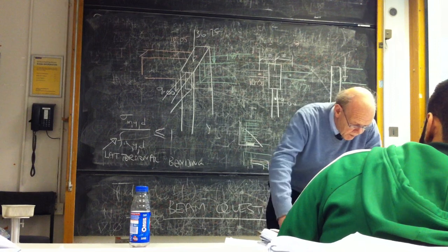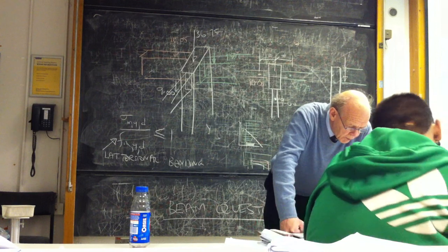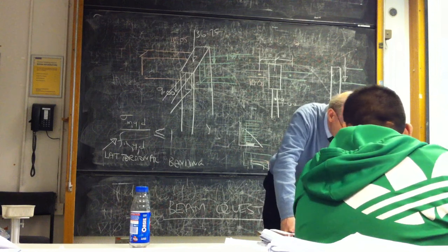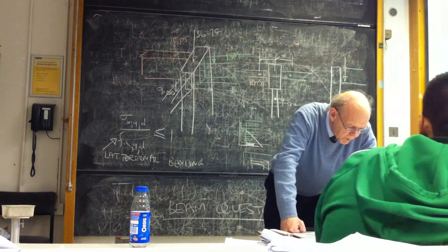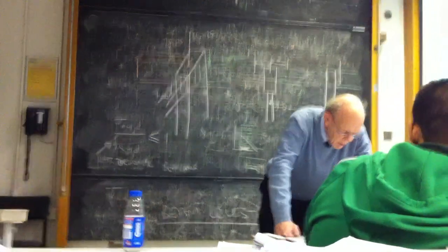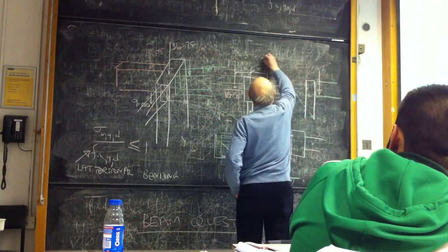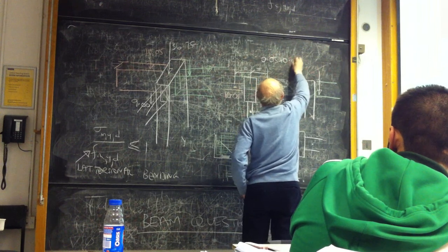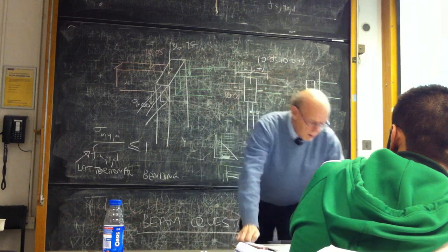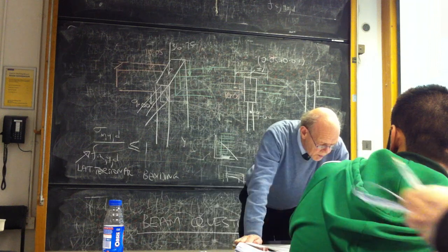Right, so what have I got? I've got the axial load. I've got the actual compressive stress at 0 degrees to the grain, 3.12. I've got the bending moment, which is the difference of the loads times the eccentricity. In my problem, this one is 0.05, is 0.07, it is distance. I've got the bending stress about the z-axis, I've got the bending stress about the y-axis.